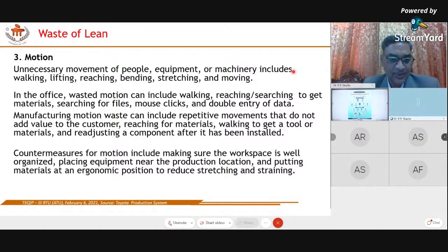One is the takt time, meaning the rate of manufacturing between the stations. If you take the earlier example of the U-shaped layout versus the traditional, conventional manufacturing layout, the item moves from the lathe machine to the milling machine, from milling to grinding, from grinding to the drilling machine, and then to the finished product. Suppose the lathe machine takes 2 minutes, the milling machine takes 1.5 minutes, and the grinding machine again takes 2 minutes. So moving from the lathe to the milling machine, the milling machine has to wait for 0.5 minutes, and similarly from the milling machine to the grinding. Grinding takes 2 minutes, and the items moving from the milling machine to the grinding machine make a pile up at the grinding machine.